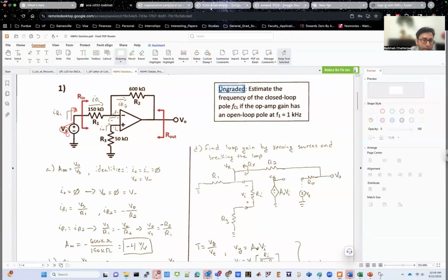Now, for that, remember that even though you're trying to find out input and output resistances as the Thevenin equivalent resistance at the input or the output side, the existence of the op-amp actually forces some of the points to have a particular amount of voltage. Because in this case, just as an example, you already know that because there cannot be any current going into the op-amp, this current going into the non-inverting terminal of the op-amp is going to be 0. If the current is 0, the voltage drop across R3 resistance is going to be 0 from Ohm's law.